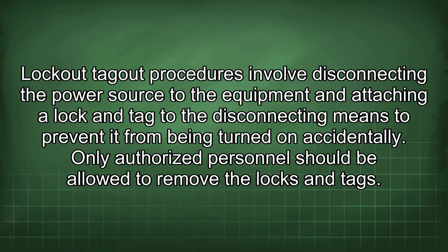Lockout-tagout procedures involve disconnecting the power source to the equipment and attaching a lock and tag to the disconnecting means to prevent it from being turned on accidentally. Only authorized personnel should be allowed to remove the locks and tags.